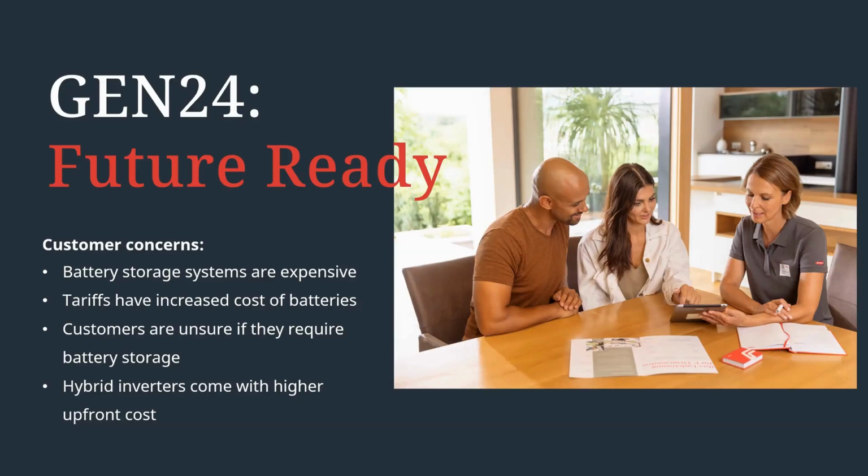If the customer doesn't need a hybrid inverter or they're not looking for a battery, they can install the Gen 24, save a little bit of money. And then if the case needs a battery later on in its life, again, as Mark put it, a customer gets an EV or electrifies their home in another way, the Gen 24 can just be upgraded to a hybrid inverter, and it can be done at any time.